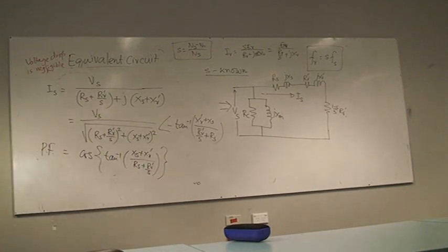So that's my power factor. Could you theoretically have three different power factors if you had a different level of inductance in each coil? Well, if this is one coil, and this coil has a power factor built into it because it has an inductance and a resistance, if you built the coil separately, could you theoretically have a combined power factor? No. Any coil will have only one power factor.